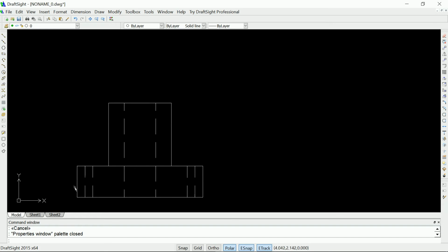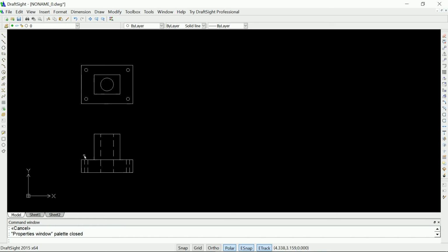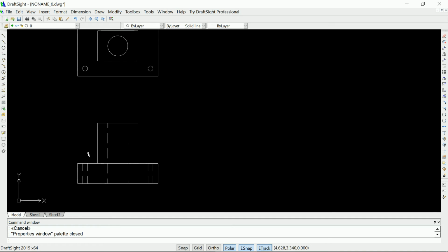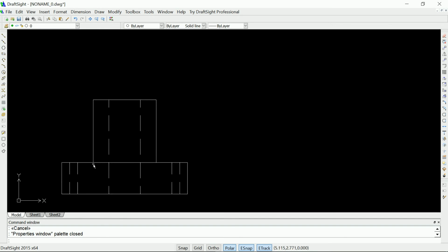Now, you would normally, if you're machining this, you might not want to go with a sharp corner here. And in that case, you could put a radius. But before you can put a radius with DraftSight or AutoCAD, this line has to intersect with this line and only the endpoint. So this is a continuous line. You have to break it up.